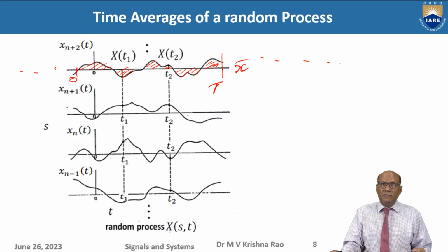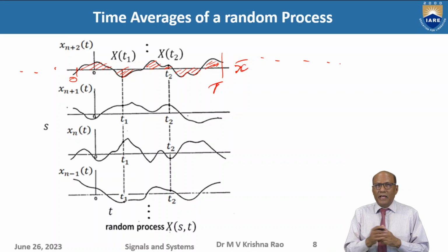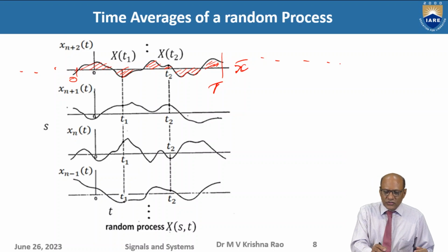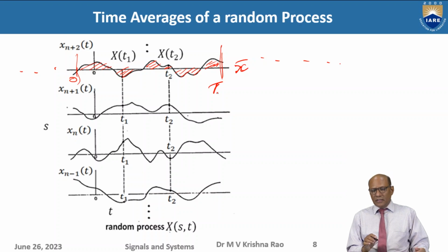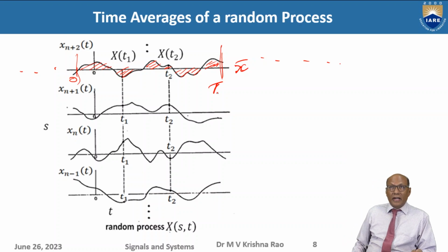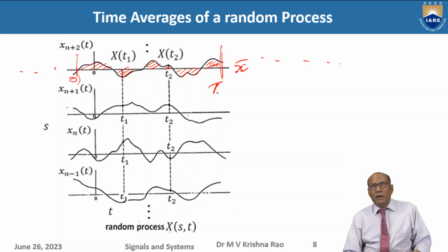Okay, so we cannot define the infinite energy. So you have to take some time, and then you can define the power. So energy in a certain duration, within a window time slot, you find the area, then divide it by the time. Okay, that's why random signals are also called power signals.